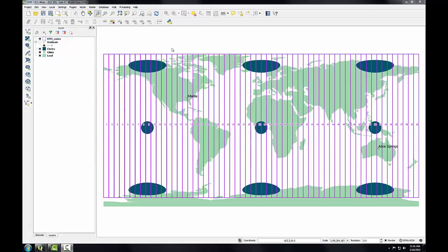It's the UTM zones. We've just covered the state plane coordinate system, and UTM is similar to state plane in some respects. It is comprised of zones. However, Universal Transverse Mercator, known as UTM, is a Cartesian or plane coordinate system that spans the entire globe. It's probably the best known Cartesian coordinate system of international scope. In the UTM system, the globe is divided into 60 zones, each comprised of 6 degrees of longitude.